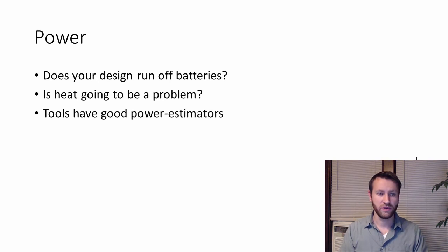In general, the tools have good power estimators. So you can get a pretty good feel for how much power your design is going to take by running through the power estimator tool. You've got to tell it your clock speed, how many resources you're using, flip-flops and block RAMs, and whether or not you're using external interfaces. That's the other big contributor to power. So if you have a DDR interface to hook up to external memory for your FPGA design, that's going to take a lot of power. SerDes, high-speed serialization, deserialization, takes a lot of power. If you don't know what I'm talking about, don't worry about it. You don't have to worry about it.